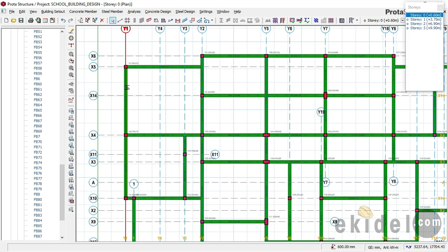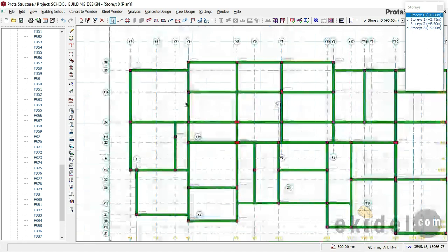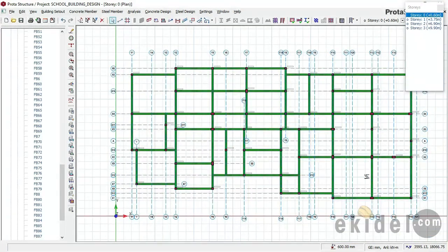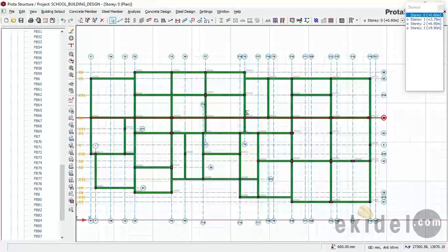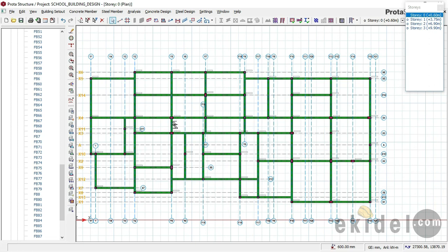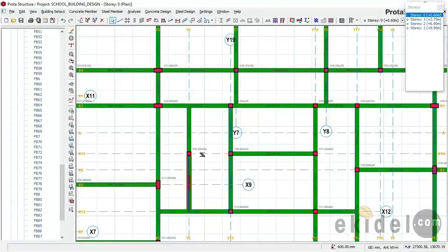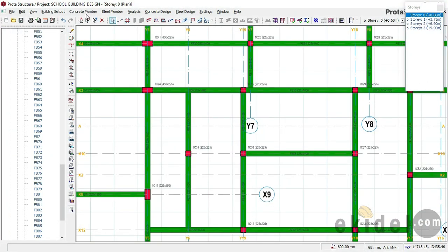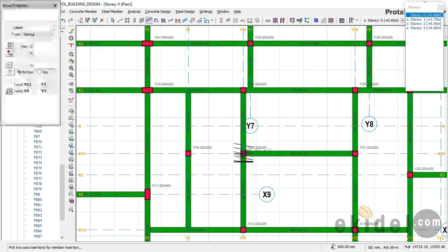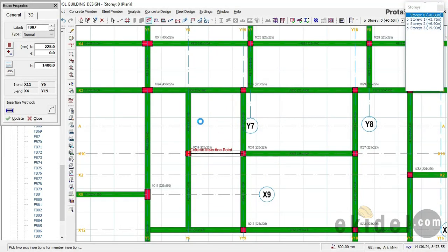Since none of the lengths is up to 6 meters, that is fine. Okay, so I can take this right now as a panel. This is 5.25 multiplied by 5. That's fine. So right now I am done with my ground beam. I can see my ground beam arrangement there. I can choose to connect this beam together here, just to make this connection stronger. Okay, that's fine. I can choose that.